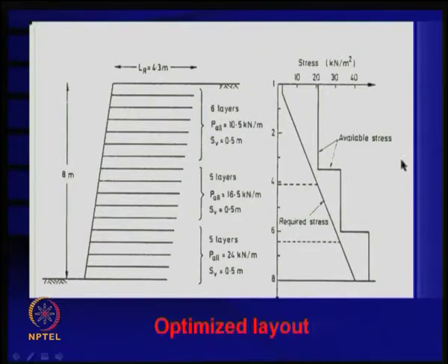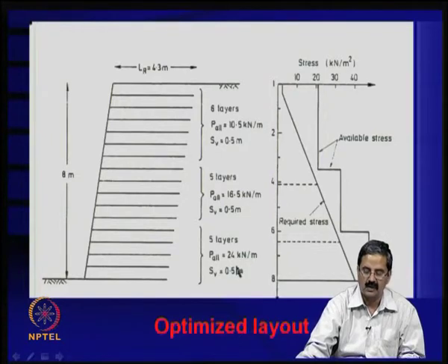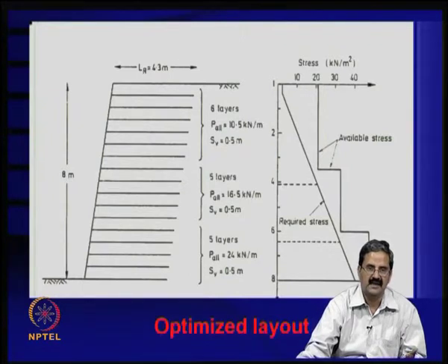So, it is very useful to note that the way we calculated the design also directly included the factors of safety, because we got these numbers based on time extrapolation, damage effects and all that. Whatever the numbers were, we have considerably reduced them and got the design. So, this is the length of the reinforcement required, this is the spacing required, and this is the type of geogrid required. This is the answer. If I want to say that this is the suitable reinforcement configuration, yes, this is that.